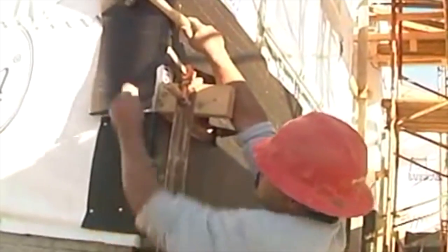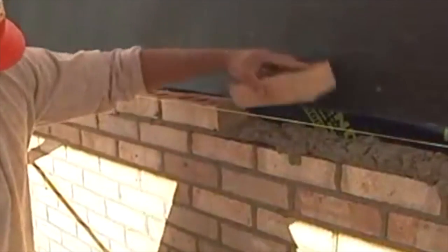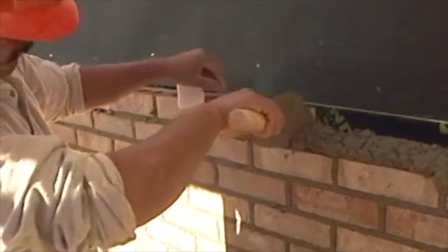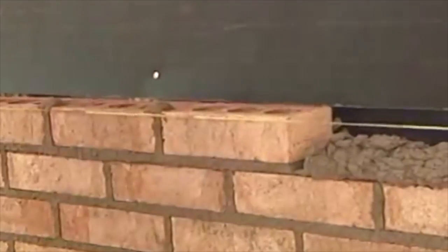The second layer is a capillary break, which can minimize water transmission due to mortar bridging because of the mortar dropping from wall ties. Weep holes are critical drainage features because they allow water to drain out of the wall cavity. Weep holes can be created with this spacer product or clear opening, which must be spaced at a maximum of 16-inch on center or 24-inch on center respectively.